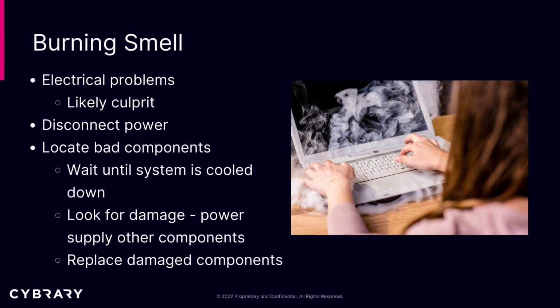Burning smell. You should never have a burning smell from your computer. If you do have a burning smell, most likely it's going to be electrical problems. Find the source of that smell. Disconnect the power right away. Locate the bad components. Wait till the system is cooled down, of course, and you'll see damage on those components, where it may be melting or maybe dark or burned areas on those components.